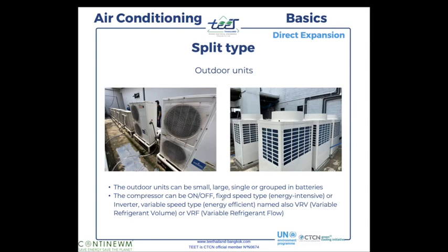So you need high speed of the compressor. If the heat is lower, you need less gas, so the speed is lower. If you have a small heat, the speed is lower, okay? So that is more energy efficient because the speed of the compressor can be adapted.